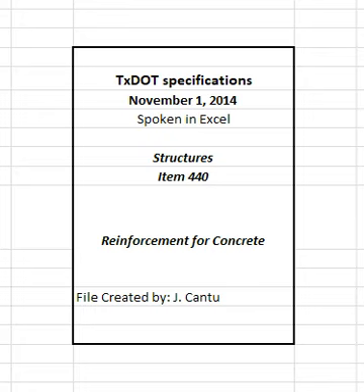2.8 Mechanical couplers. Use couplers of the type specified in DMS 4510, mechanical couplers for reinforcing steel, Article 4510.5.a, General Requirements, when mechanical splices in reinforcing steel bars are shown on the plans. Furnish only couplers pre-qualified in accordance with DMS 4510, mechanical couplers for reinforcing steel. Ensure sleeve wedge type couplers are not used on coated reinforcing.